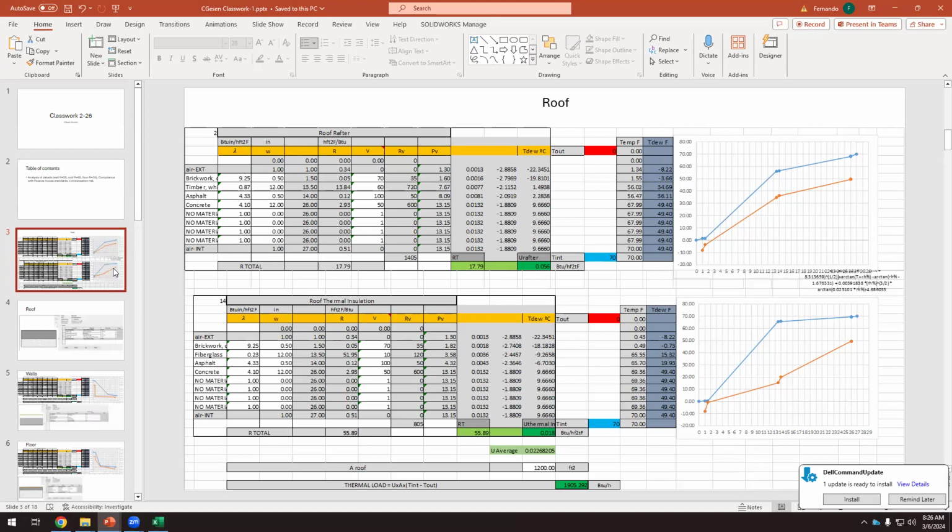If they don't seal this well, they can have condensation issues, even though they have used the vapor retarder in the right place. So at least with this detail, we don't have this condensation risk. But if the assembly of all the materials is not correct, no matter how good your wall is, you can end up having this kind of condensation there.